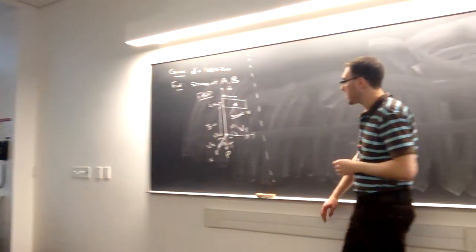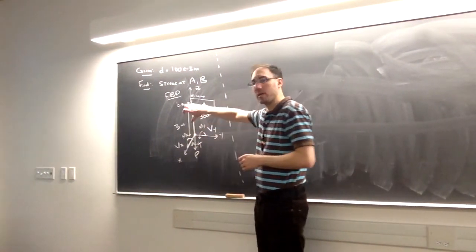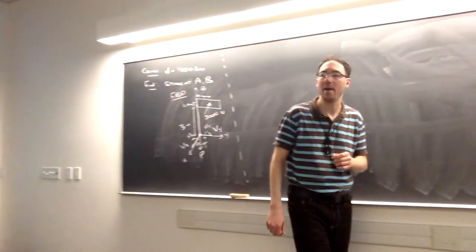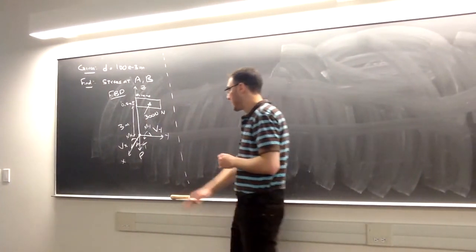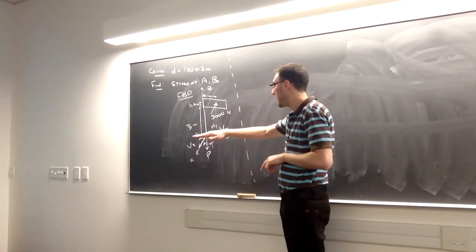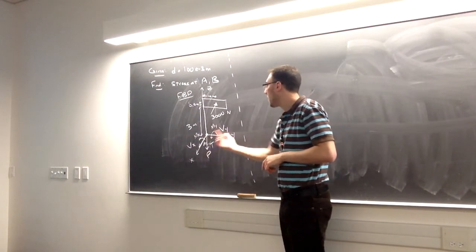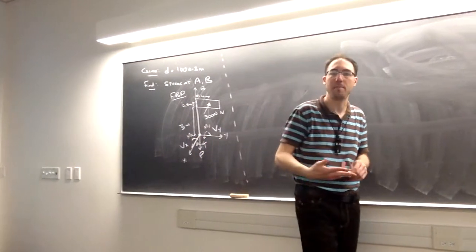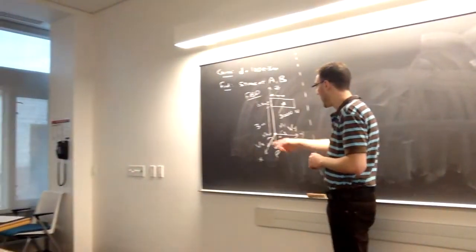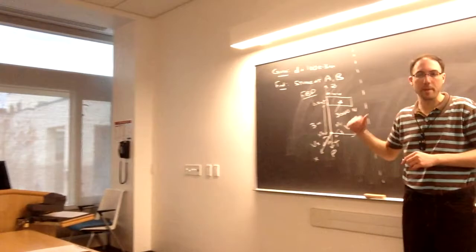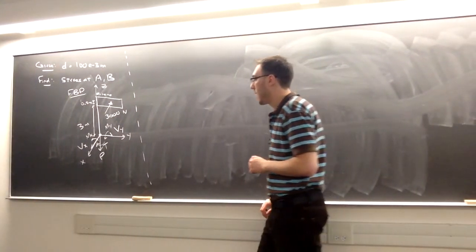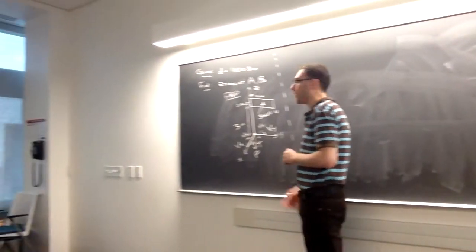So again, I'll reiterate, the force P always comes out from the surface of the cut. T we're going to assume is positive around that force P. And then since our coordinate system will, in these cases, always be in line with our surface of the cut, we can split our shear force into two components along the positive axes, and our bending moments around the positive coordinates, again assuming positive directions for both. Questions about the free body diagram we have for this one?